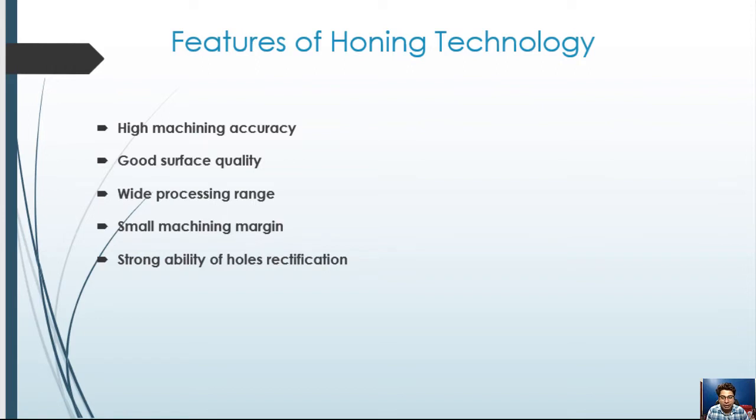It is possible that straightness can reach within 0.01 mm to 1 meter if there are no ring grooves or radial holes. The accuracy of honing is higher than that of grinding, because the bearing support of the grinding wheel is located outside the hole when grinding. It is a reason for the deviation.